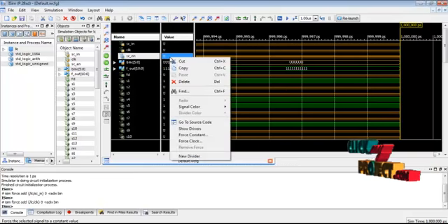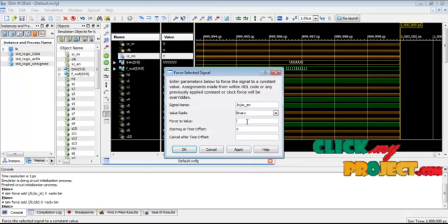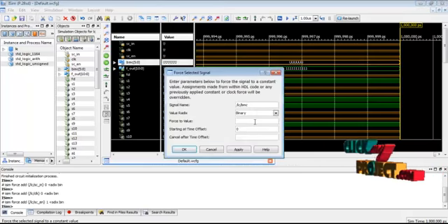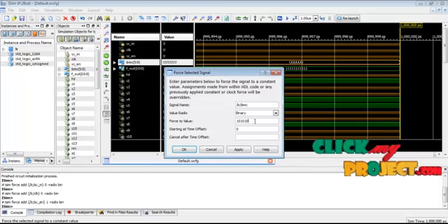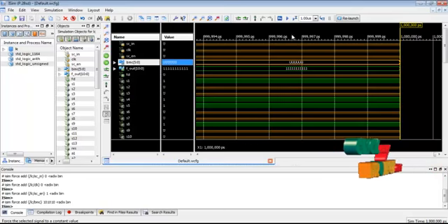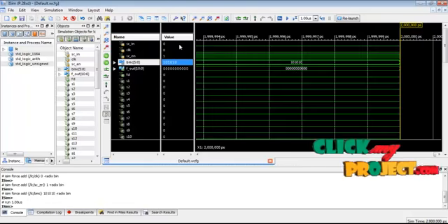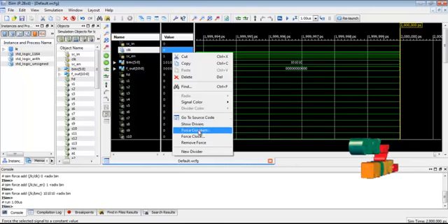The clock is initially applied as 0, then the scan enable is activated. For the benchmark circuit input, we apply any input. We run for the time specified on the toolbar. Next we apply the clock 1 results.